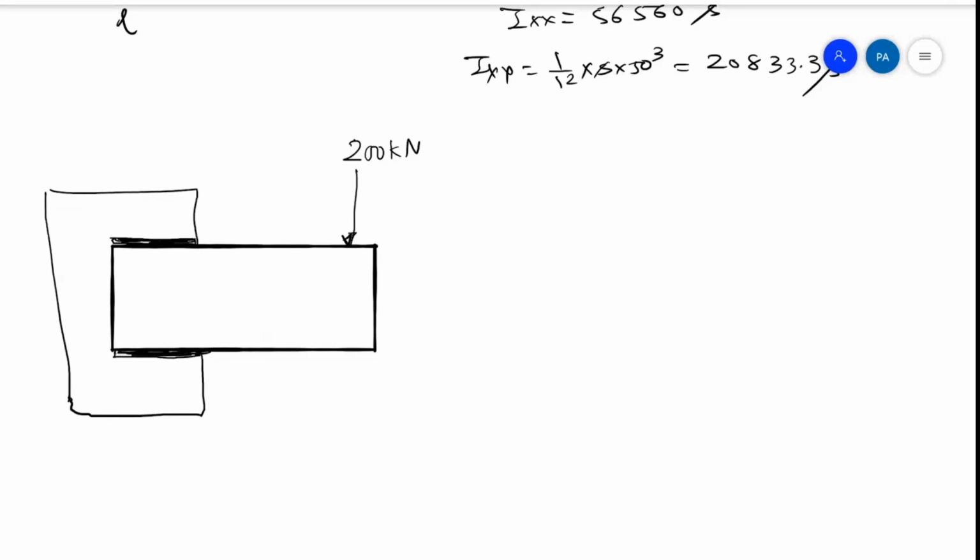And in addition to this, now where is the CG of this line? The CG of this will lie here. All of you understand this now? CG will lie here, correct? If this is say 50, CG will lie at what distance? 25. All of you understand this. But the moment I say that I weld it from here also,